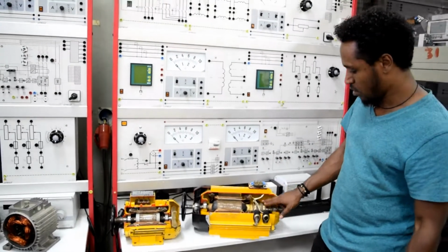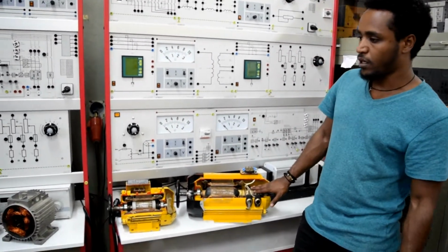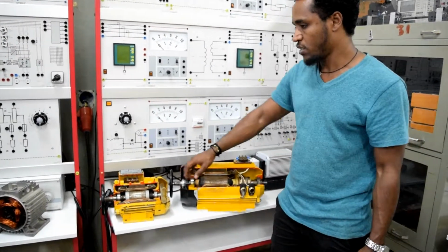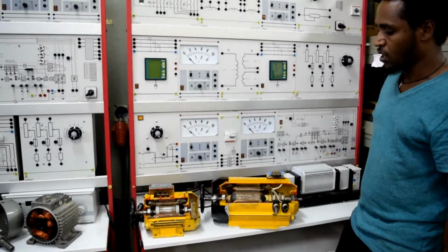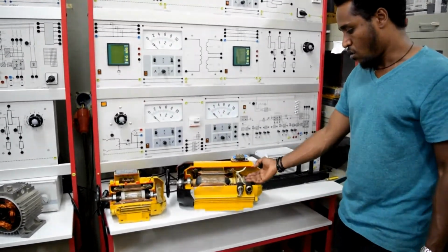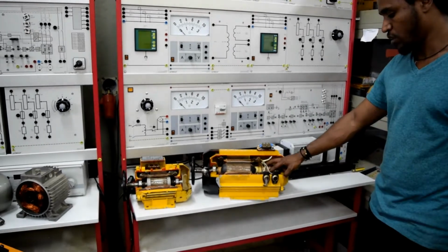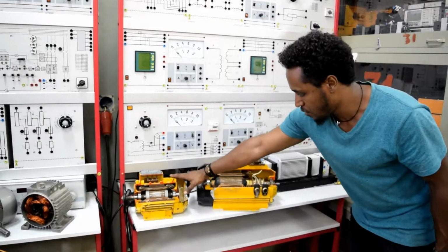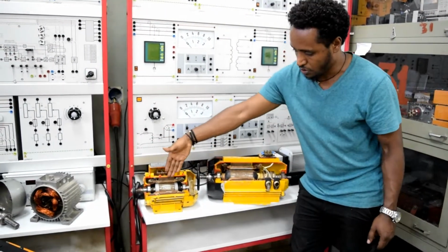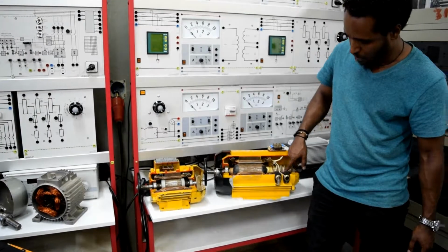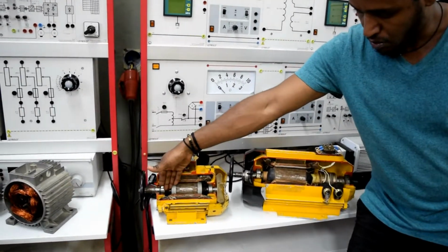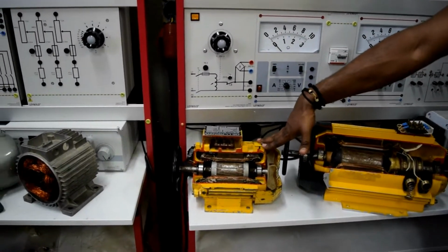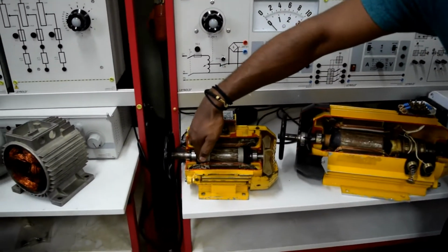So as you see it here, there is no slip ring here, but there is a slip ring here. If there is a slip ring, there is a loss, and the efficiency for a squirrel-cage is higher because there is no loss due to brush contact with the slip rings. So the efficiency is more, and it is cheaper and rigid in construction. As you see it here, it's cheaper because there is no slip ring and no brush here, and also it has a better space factor.